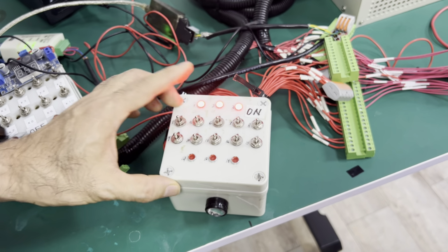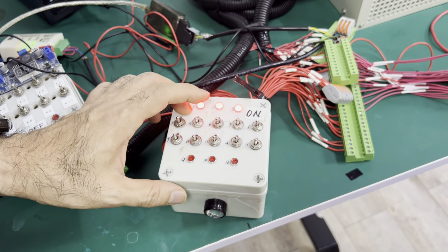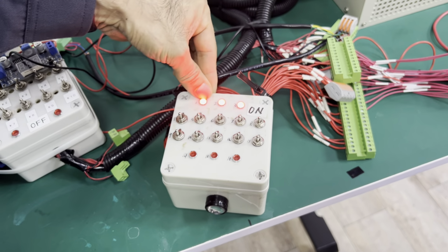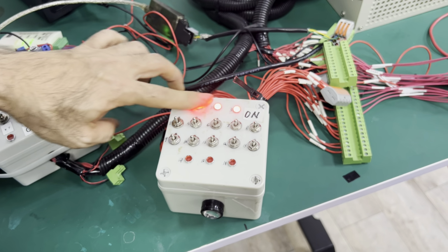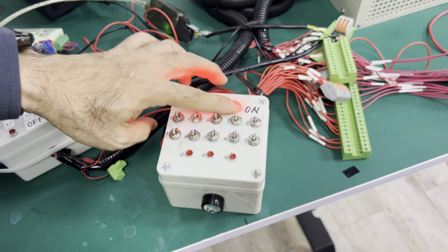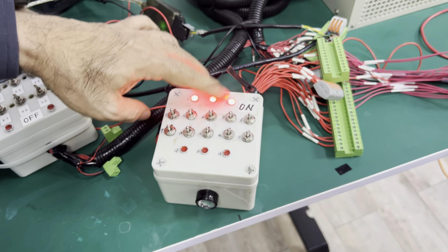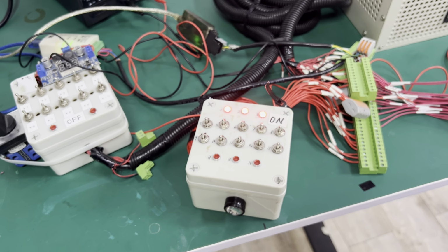So when the MCU1, MCU2, and fast charge relay are off, the feedback pins should output the ground signal, so the light will be on. This is the reason we put these three lights on this test panel as a test. Okay, let's continue.